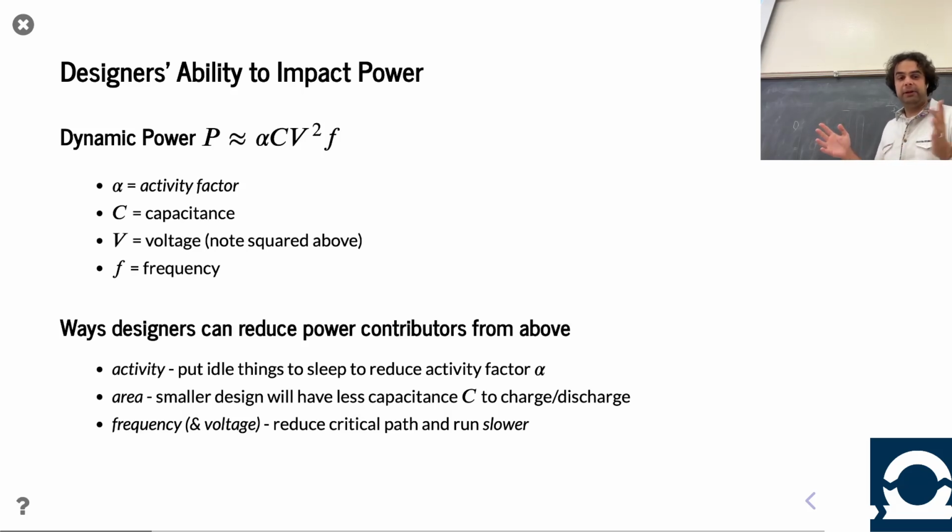And they kind of scale differently over time. In general, people make bigger designs in terms of transistor count. Normally, if life is good with Moore's law and stuff, even though the transistor count increases, transistors get smaller and their capacitance reduces, so your net capacitance might be similar. Your voltage might slightly go down over time, but then as an architect, you're trying really hard to reduce the activity factor to save energy. But none of these things hold true in the modern era. Sometimes in modern designs, capacitance isn't shrinking that much, etc.